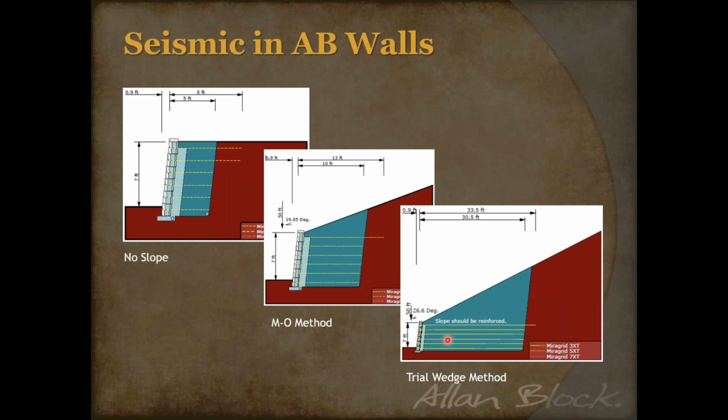They could just change it ever so slightly. They can go ahead and raise the wall height. That would reduce that slope. And if you reduce that slope, you just dramatically changed that dynamic load. Slopes and seismic, they are not friends of each other. Right? And so if you can reduce that slope, now all of a sudden, you're not getting 30.5 foot of grid. You're probably going to get back something closer to that 60, 70% grid lengths again.